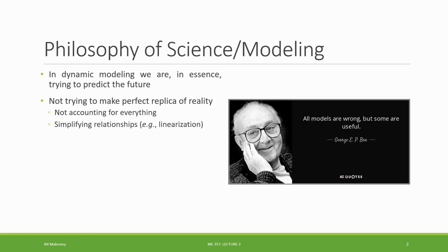If we're operating with a spring that really isn't linear in the region that we want to use it, then probably it will not be appropriate to make that linear assumption about its behavior. And certainly there are nonlinear springs, like leaf springs, that we might be interested in using. And we'll talk about that later in the course, but for now, for the springs and dampers we use, we're going to be perfectly fine using that linear relationship.